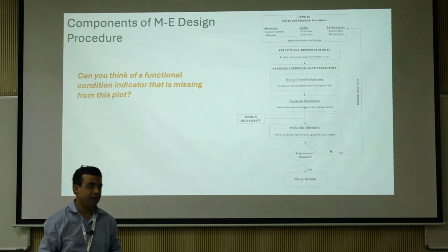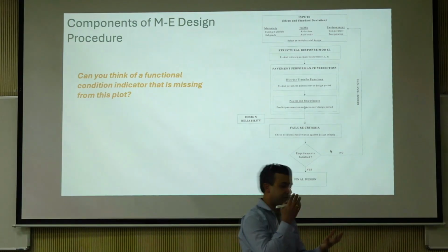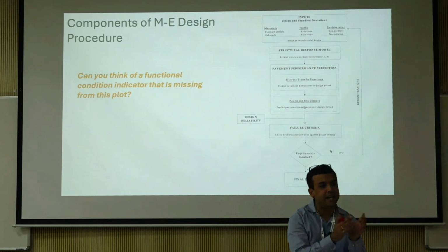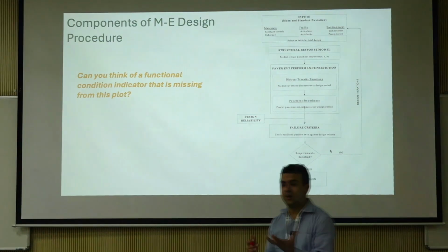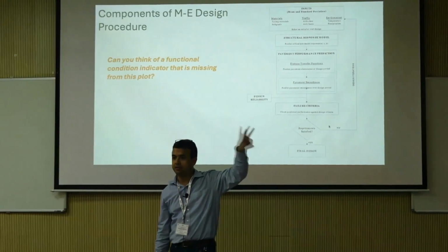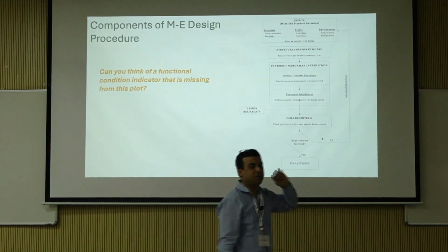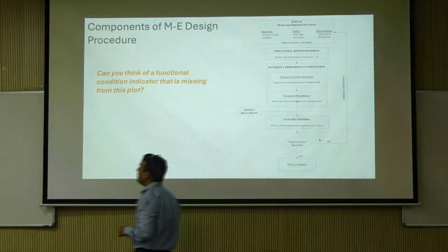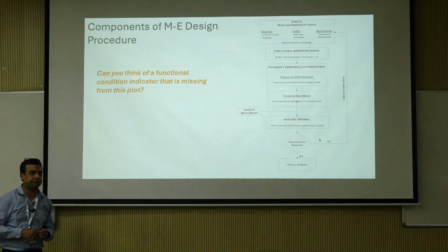So in the mechanistic empirical pavement design guide, for subgrade soils, aggregate bases and so on, density is not a direct input into your mechanics. What is a direct input is your modulus and your Poisson's ratio, right? Those are the two things. So the level of input in a mechanistic empirical pavement design guide, there is level 1, 2, 3.